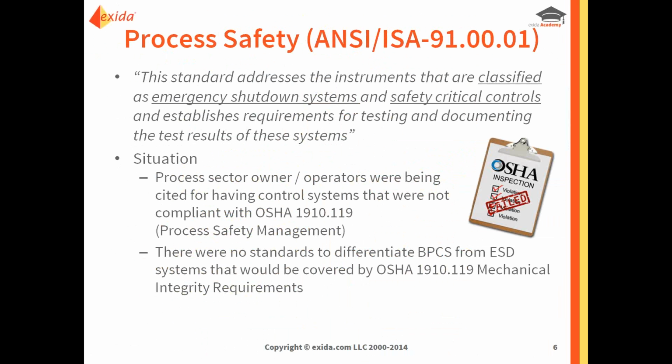of OSHA PSM. So the purpose of this standard was to be able to differentiate, to classify the control system as a BPCS versus an emergency shutdown system, so that only the control systems that were called or treated as emergency shutdown systems would be those that would be reviewed by OSHA and would need to comply with the PSM regulation.